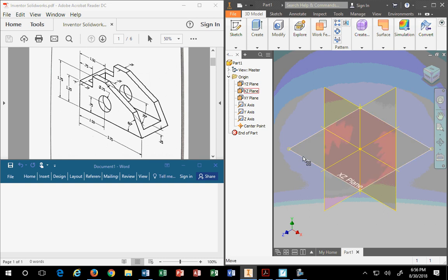This is called the XZ plane, what you are accustomed to calling the XY plane. And I know that, because as a machinist, that's what we look at, right? And we're going to program the CNC. It's okay. The product is able to work with the CNC without a problem, even though it uses this terminology. Don't worry about it. But just so you're aware, that's what it's doing.